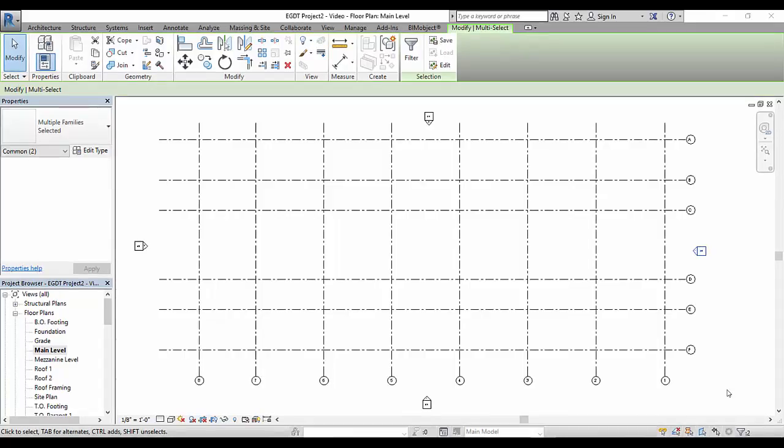This tutorial will cover laying out the walls, floors, floor slab edge, and footings for Project 2. Referencing our handout, we can read that the warehouse walls are a W1 wall type, which is a basic wall exterior 8-inch split face CMU. This is the only wall type that we're going to make an edit or a change to.